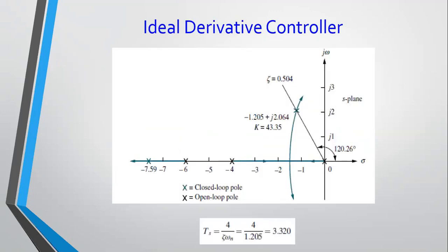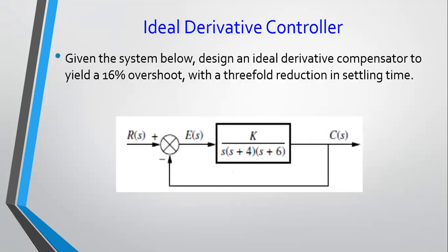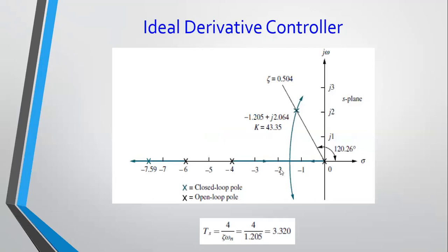The first step is to sketch your root locus. If you go back one slide, you've seen we don't have any finite zeros. We have finite poles at 0, -4, -6. So you first put in your finite poles, and from there you sketch your root locus, get your branches right. You can see here you have one pole on this path, which is not going to influence the transient of the system. That's not the dominant pole. The dominant poles are here.